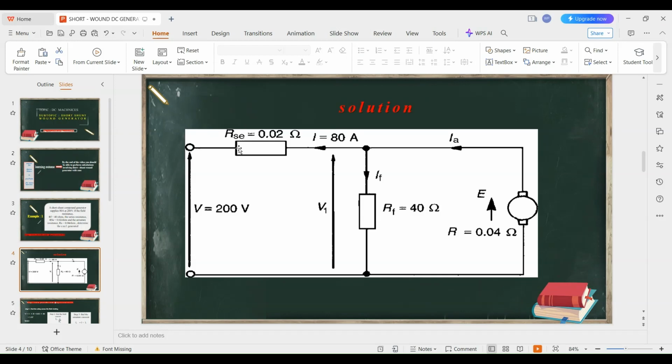Using the previous diagram that I had drawn in the first example, we have seen that the terminal voltage will be given by adding all the voltages across that circuit. That is the supply voltage plus the voltage drop. Our supply voltage is 300 and our voltage drop is 1.5. Therefore, our terminal voltage will be 301.5 volts.